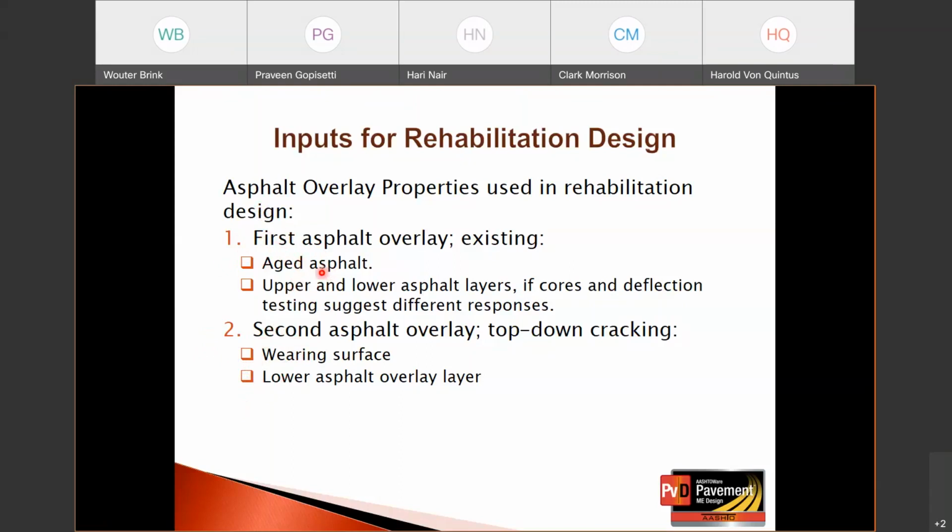And as I noted earlier, we're only going to have 1 asphalt layer in 2001, because that's what all the data in the core suggest. So that's exactly what was done. And then the second overlay can either be 1 or 2, depending upon the thickness of that overlay, on whether we want to simulate 2 different lifts or 1 overall asphalt overlay to be placed.